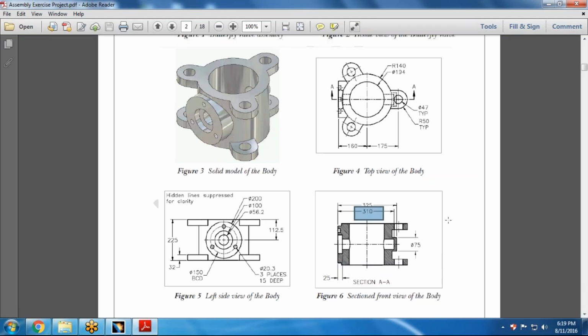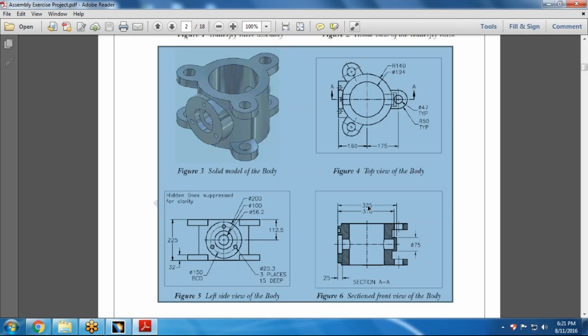The dilemma is this, that the distance from this corner point, you can see this point, the length is 310 to this pocket, but this pocket cannot be created by 310 just because the overall length is not equal. Like you can see there, that is 160, and if I am just getting the radius of this, which is 140, so 160 plus 140, how much? The size will be around 300. So if I have the solid component of 300, how can I create the pocket of 310? This is not technically possible. So we have to make a part up to 325.